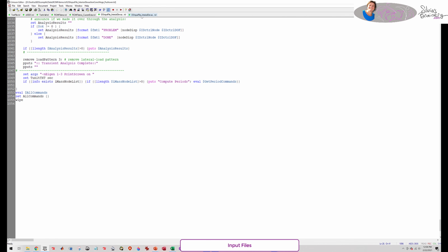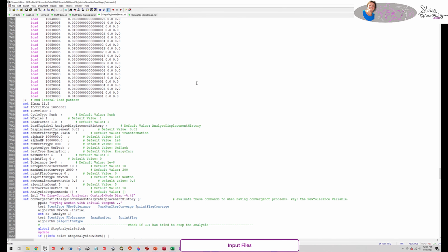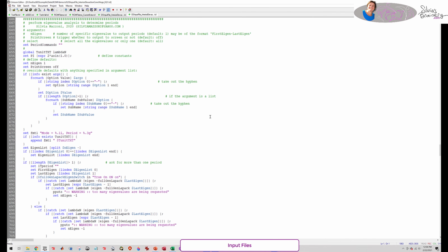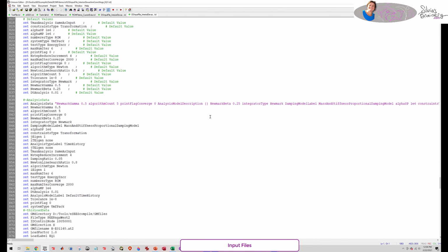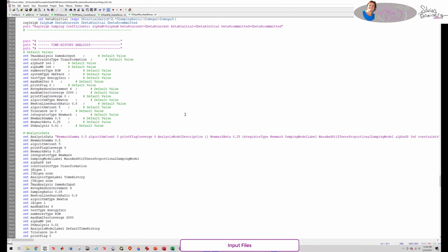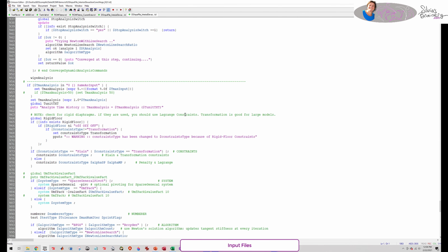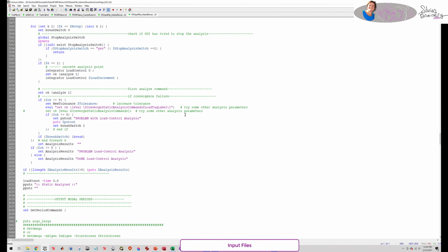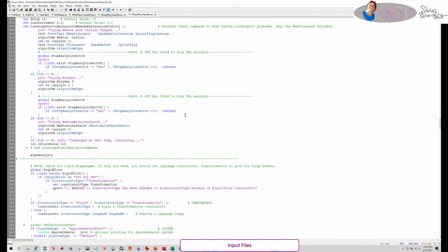But of course, if you need to do something special, you can always use eSEES to start off, build this OpenSees input file, and then start working on this. You can't go back to eSEES because you lose a lot of metadata, but I think it's also a good way to start building a model if you're doing something complicated. And same thing with the ground motion, everything is the same until you get down to the input and the fact that you're doing a time history analysis. Again, you can go and put this into loops itself, or you can work with this OpenSees input file yourself. So this is kind of nice, and that's what eSEES does.